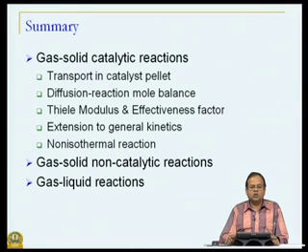What does this Thiele modulus depend on? It depends on the operating conditions such as concentrations, partial pressure for a general kinetics. It depends on the rate constant of the reaction, it depends on the diffusion coefficient.